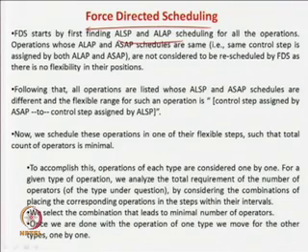So, what is our idea? Our idea is that we are basically trying to find out in which part of the circuit which is a better algorithm. So, obviously you have to apply first as soon as possible and then as late as possible, and then try to do some hybrid among these. But the hybrid nature we tried in the last example was not good. That is, manually we were trying to find out that this part of the circuit is good, that part of the circuit is good. That is not a very good way of doing it. So, in force directed scheduling, we start with as soon as possible and as late as possible. So, we do that.